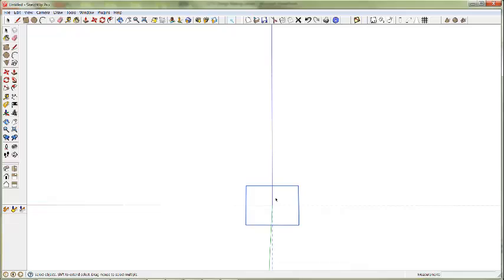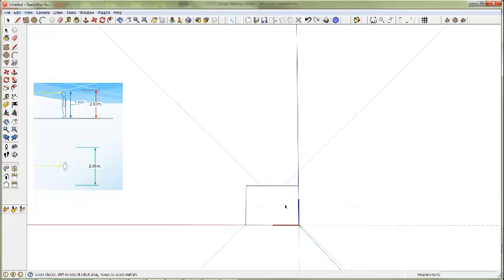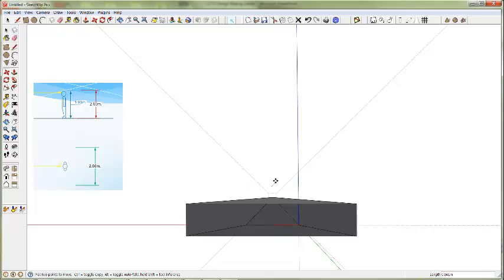Okay, so now we're working with an imager that is dimensions in the range of millimeters, but the field of view is in the range of meters. The precision there is significantly different, so I'm basically going to ignore the dimensions of the imager. What I need to do now is move the horizontal and vertical edges equidistant, so they have a 2 meter displacement between the vertical edges and a 2.66 meter displacement between the horizontal edges.